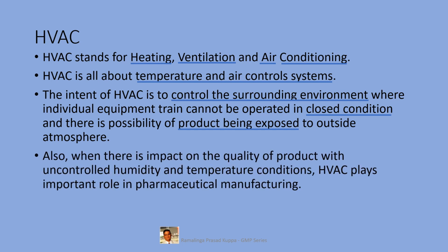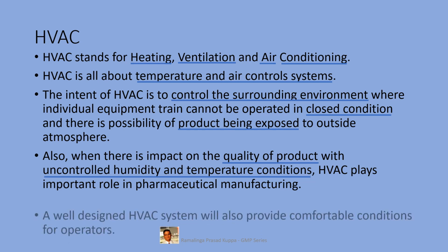Also, when there is impact on the quality of the product with uncontrolled humidity and temperature conditions, HVAC plays an important role in pharmaceutical manufacturing. There are several products which are sensitive to temperature and humidity. It is particularly important when hygroscopic products are handled. So, the HVAC should be designed to control the temperature and humidity also. The specifications depend on the product being manufactured.